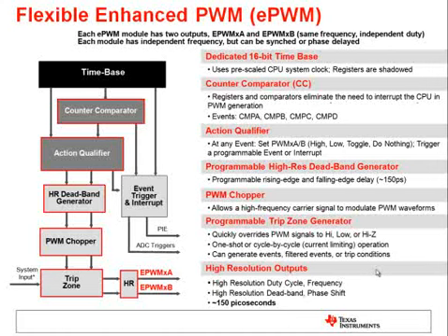Concerto's ePWM modules are very similar to Piccolo's PWMs, so if you've worked with them before, you'll find it very familiar. Just to recap, each PWM module has a dedicated 16-bit time base and supports 2 PWM outputs. The time base module contains logic for synchronizing with subsequent or preceding ePWM modules as well. It then passes on the time information to the counter compare module and the action qualifier module.